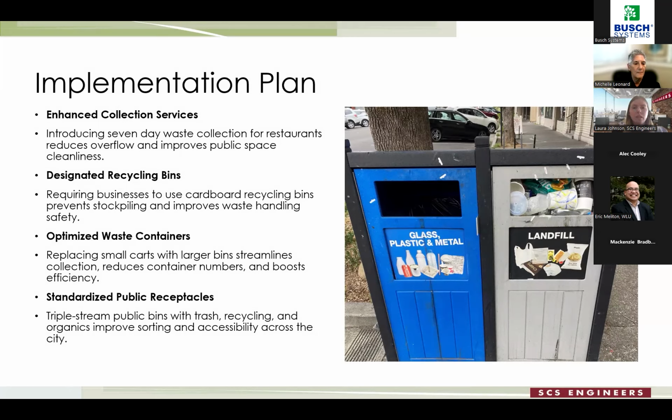So one of the main things that we felt would be useful for the city was introducing a 7-day waste collection for restaurants and those high impact generators that we touched on. While we were in the field, we noticed there were high instances of overflow. They were already maxed out on the 6-day collection frequency. And so we implemented this recommendation to add a 7th day of collection for some of these larger generators.